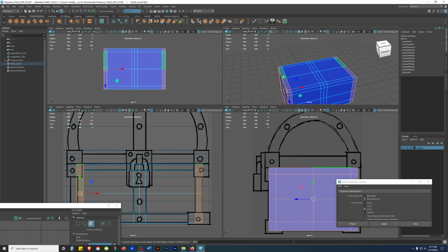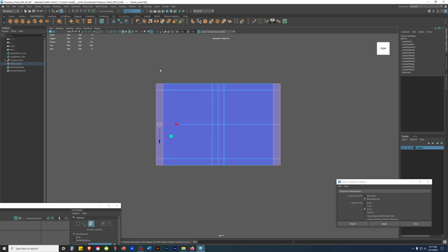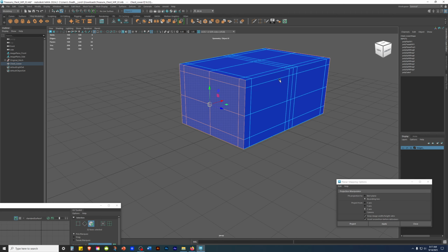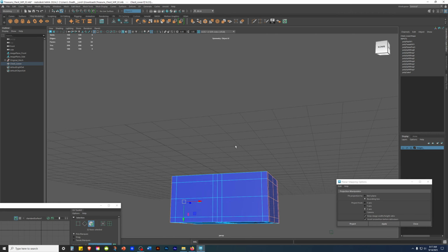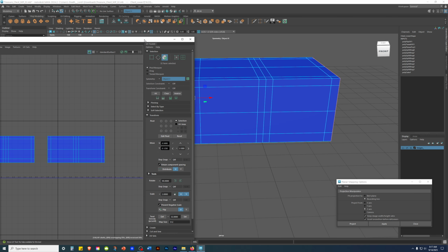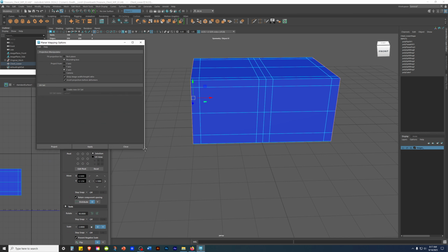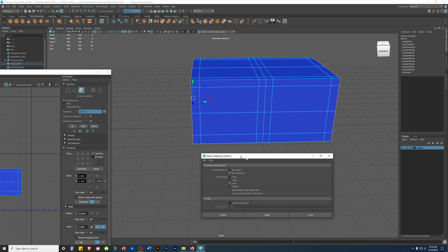I don't need this. So in here, holding control, drag like this. That makes it, holding control will deselect that area. Now that allows me to quickly grab that and that. And here, again, planar mapping.